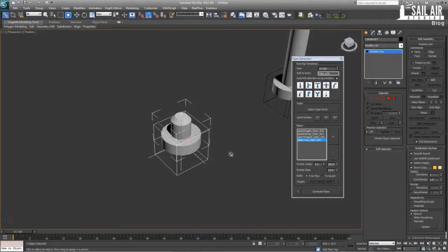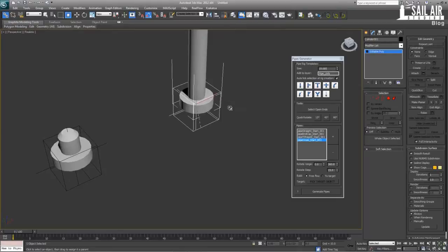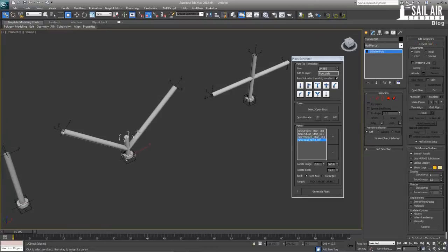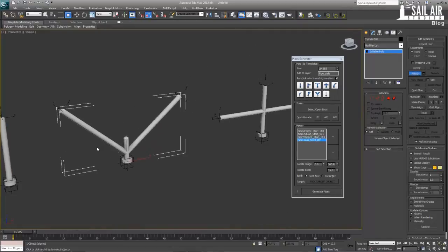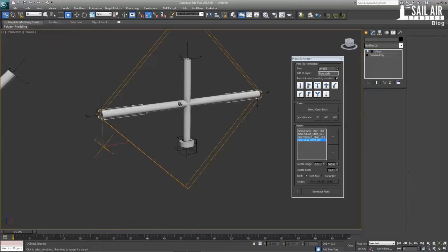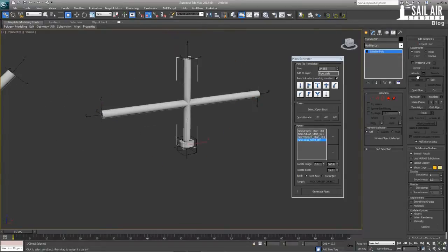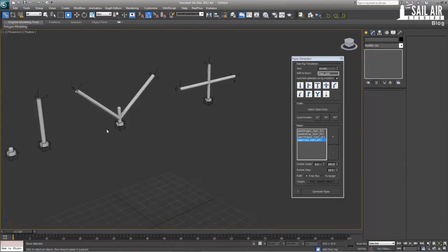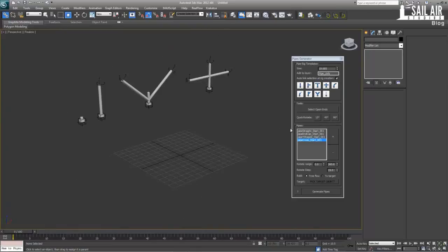Select the link, and there we go. Select the link, there we go. This is going to need a bit more, as well as this one. As you can see, there are 3 pieces to this right now. It's simple to attach them, and that's what we need to do. What it does is it now allows us to select and link this one piece of geometry to this area. I don't know if you need to attach them, but I would just be on the safe side. It makes more sense. Instead of parenting them twice, just right click and attach. And select the link. Instead of having 2 things parented to the same object, it just has one full editable poly. And you shouldn't be editing these anyways, if that makes any sense.